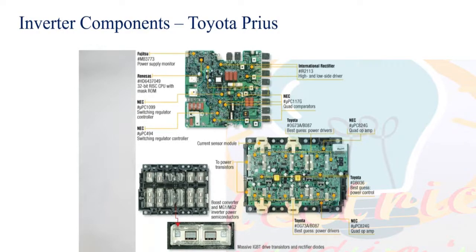If the temperatures are not sensed properly, it will directly damage the IGBTs. IGBTs are very sophisticated components, so they have to be properly selected and sized. If you wrongly select an IGBT switching device for an application without knowing the current capability it should handle, it will be very problematic. I should not take an IGBT used in a two-wheeler and put it in a car. Will it work? Or if I take a MOSFET or IGBT working in a car and put it in a two-wheeler, both are wrong, right? Both are wrong. So I have to properly size the IGBT inside an inverter.